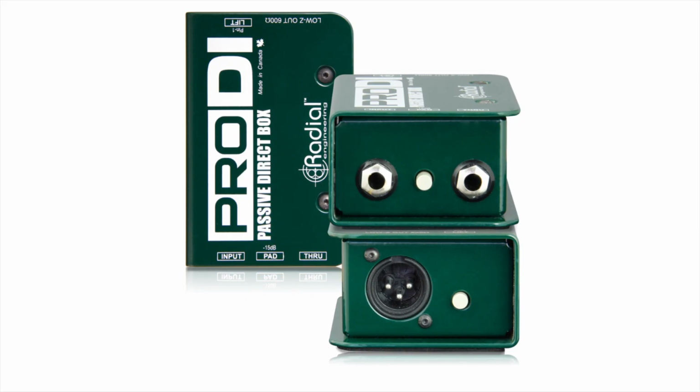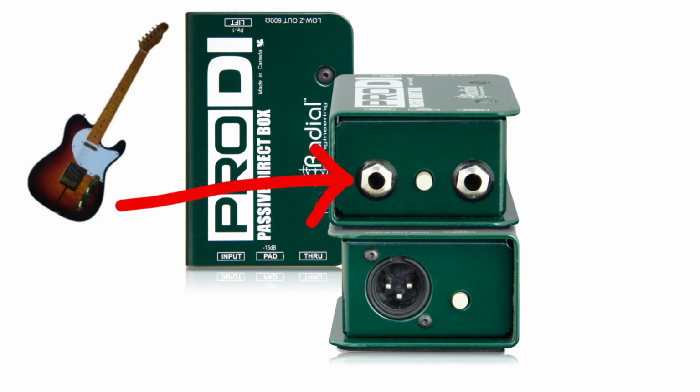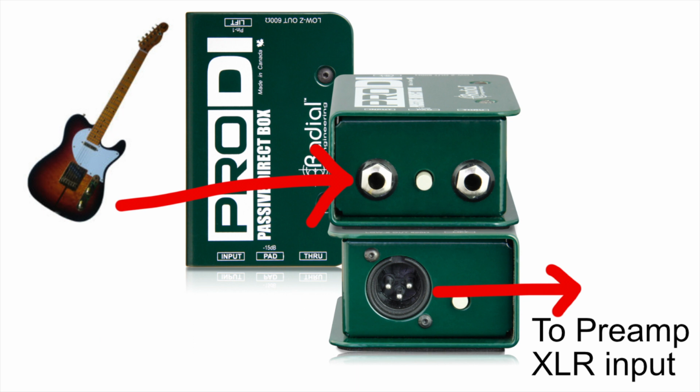So to use this, we use what's called a DI box. If you want more information about the differences between these signals, check out lesson 11 on analog audio cables. So what's a DI box? It has a 1/4-inch input that the guitar gets plugged directly into, and it has an XLR output that gets plugged into the preamp. And the DI box does all the work of converting the signal to the proper type.